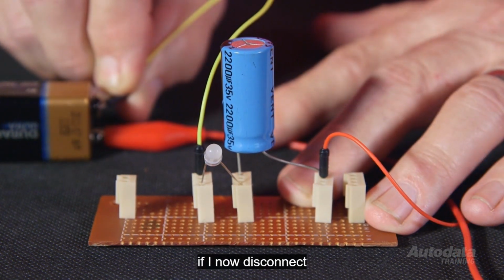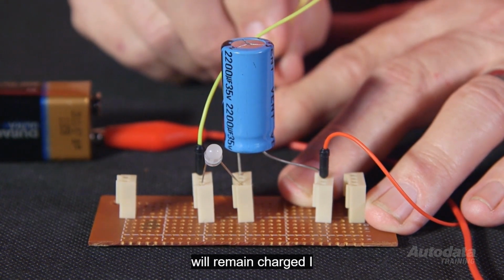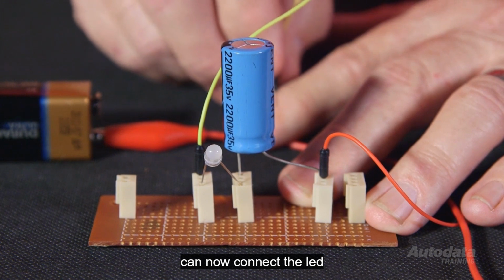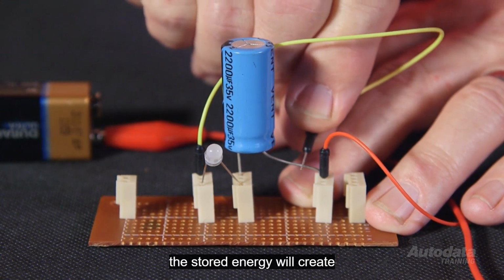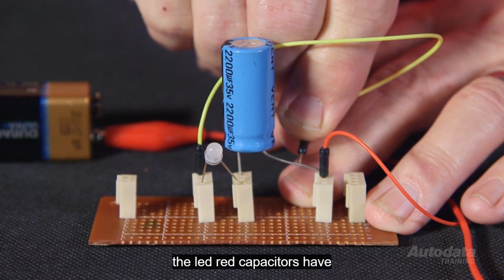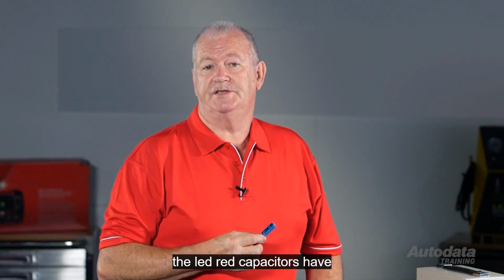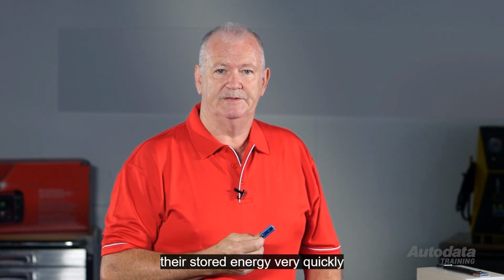If I now disconnect the battery, the capacitor will remain charged. I can now connect the LED across the capacitor, and the stored energy will create a current flow in the opposite direction, lighting the LED red.